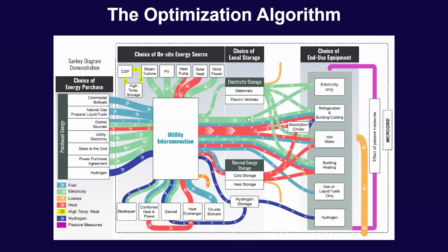And we see cases where, no, it's not the PV system charging the battery. Maybe it's the CHP system, because you get a better system efficiency by utilizing all the electricity wasted from the CHP system during the night for certain purposes and charging the battery with this, rather than oversizing the PV system in an area where PV is not that favorable. So it's a very dynamic system and a very complex system to solve, actually. And the reality is there's no way in a manual process that we can solve this and find the best solution, period.